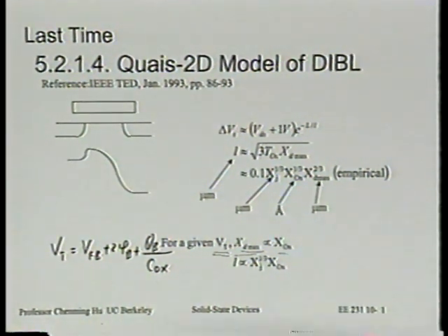In other words, you cannot arbitrarily choose a doping concentration to make XD max small. You see what I'm saying? And in fact, if you want XD to be large, which would be the wrong thing to do, you cannot even do that. If you want the right VT, there's only one particular doping concentration, together with oxide thickness, that will give you the right VT. See what I mean? And the doping concentration would fix the XD max.